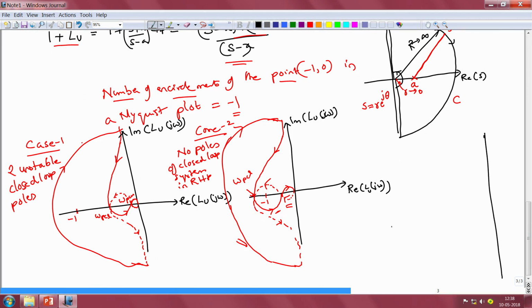So, if one were to draw the Nyquist plot once again, the x axis once again is real part of L(u) and the y axis is imaginary part of L(u), we will have that the loop gain once again starts somewhere here. As frequency increases, the gain reduces, and the first time it crosses over, namely at omega PCL, the gain is greater than 0 dB. So, the point -1 comma 0 will be to the right of this particular location,